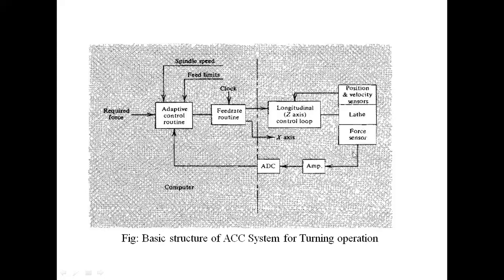So if this is 800 and we have a reference of 1000, that means we can have a cutting force up to 1000, right? Allowable force is up to 1000. Beyond that, it will fail. But currently it is 800. So we will try to ensure that the 200 difference is minimized. The adaptive control unit will ensure that.